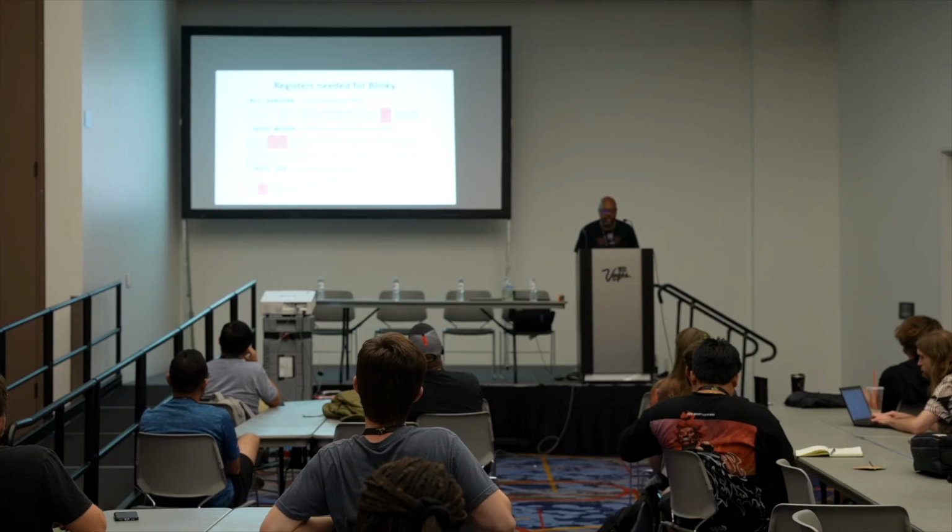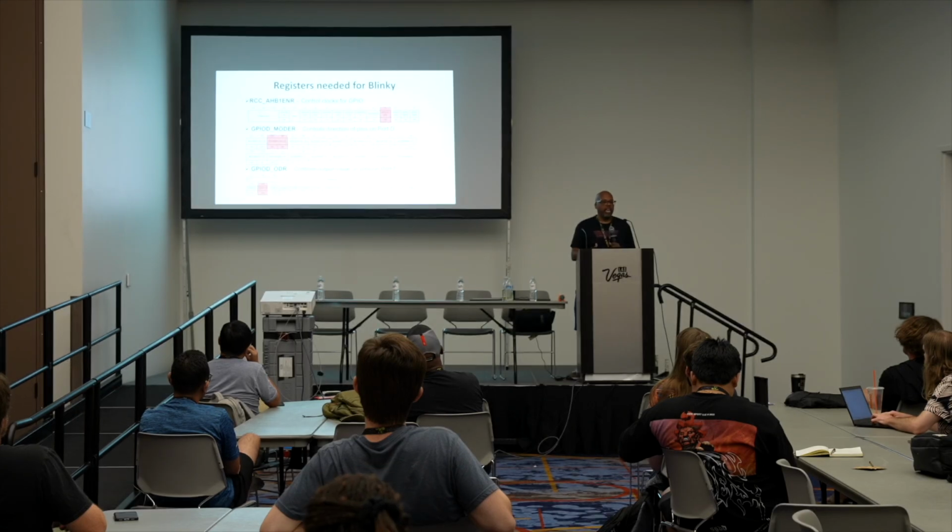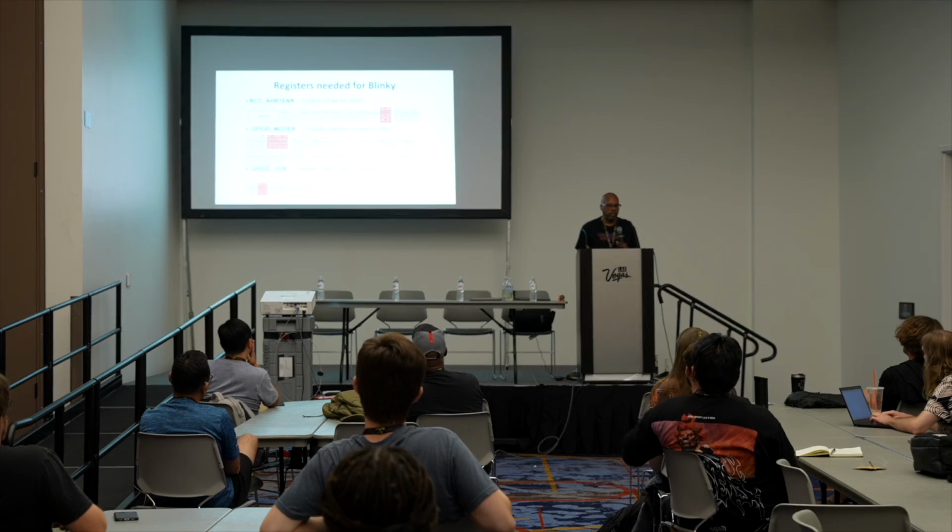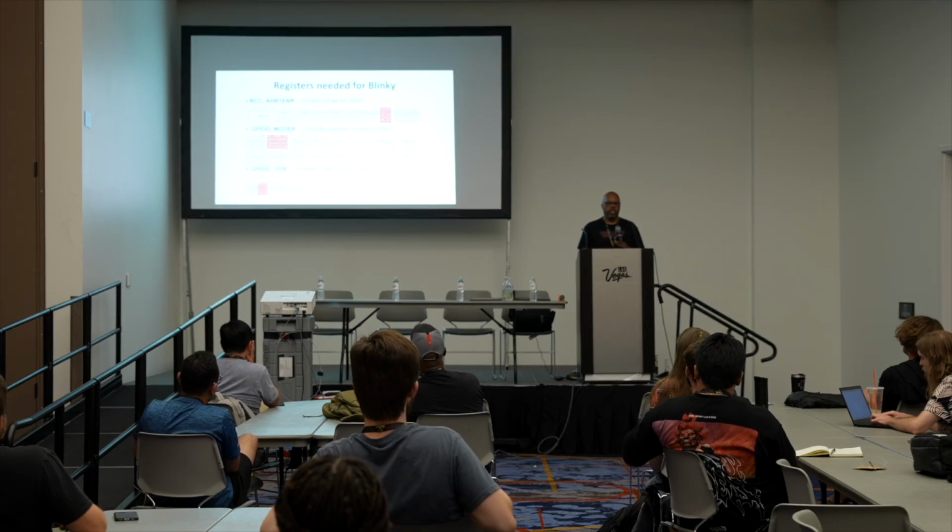Notice this register has 0 through 15 up there on the top. That's half the bits in the register. All the registers are 32 bits, so I'm just looking at the first half. If you zoom way in on this, it says GPIO-DEN for enable. And then in the data sheet, it'll say pin 3 on this register enables the clock to GPIO port D. So you have to set that bit to a 1.